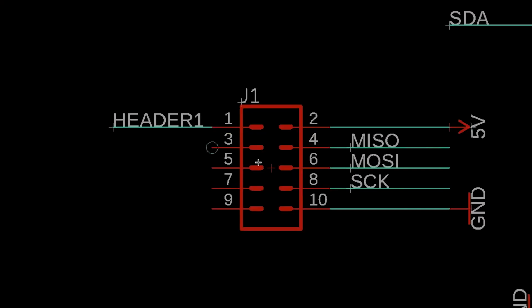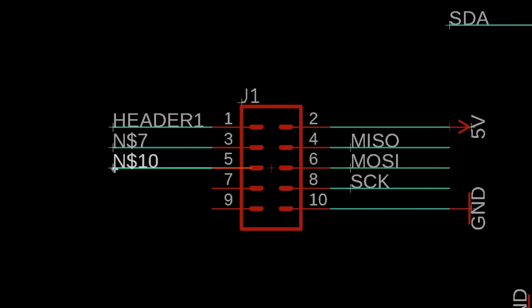Excellent. And you know, as I think about it more, it would be great to add the SCL and SDA lines. That's the I2C lines. And you know what? The cleanest way that we can do this is we get rid of all of the headers and redo them again. We're going to get rid of these and then just start clean. So header 1, 2, I'm kind of like live designing this, but here we go. Header 1, header 2, and header 3. Let's go ahead and label these.